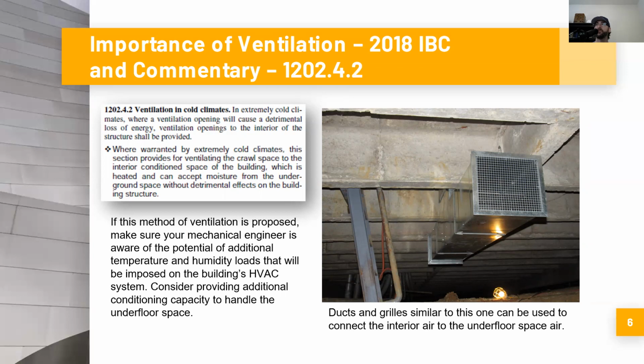And so the code now recognizes that in these circumstances, it is an acceptable alternative to actually vent into the building. So you can vent into the interior of the building and then allow the crawl space to basically breathe in and out through the interior of the building. One very important thing to consider is if this is the method of ventilation that you're proposing for any of your projects, make sure your mechanical engineer is aware of the potential of additional temperature and humidity loads that will be imposed on the building's HVAC system. Because again, in this circumstance, you're not providing mechanical conditioning or mechanical outdoor ventilation into the crawl space.